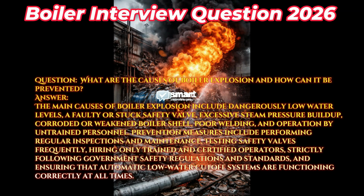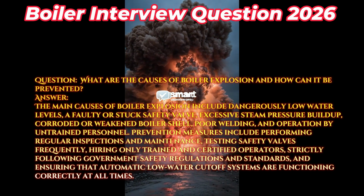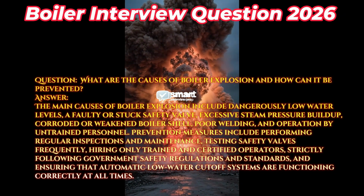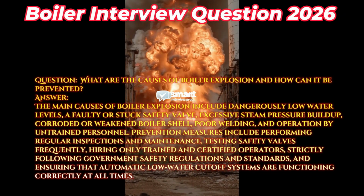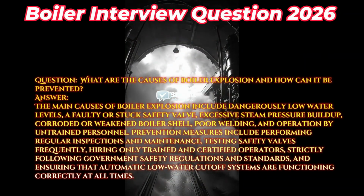Prevention measures include performing regular inspections and maintenance, testing safety valves frequently, hiring only trained and certified operators, strictly following government safety regulations and standards, and ensuring that automatic low water cutoff systems are functioning correctly at all times.